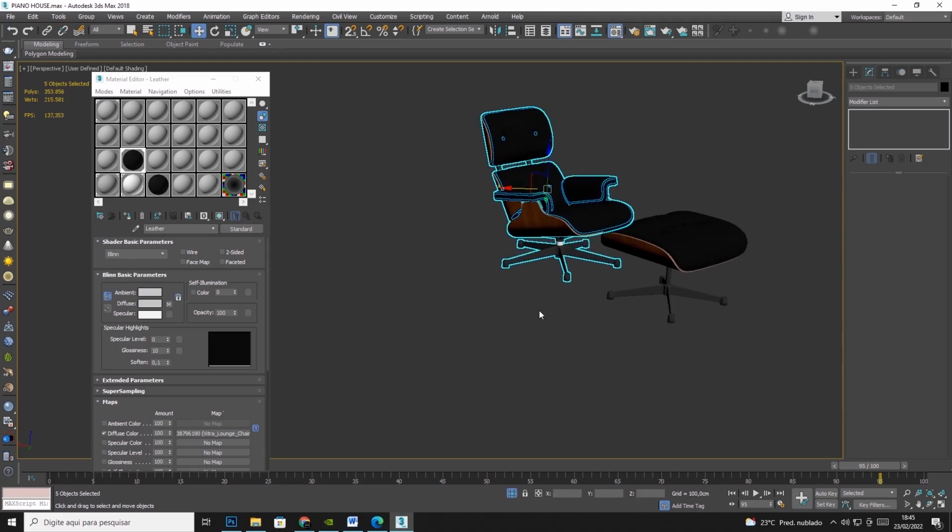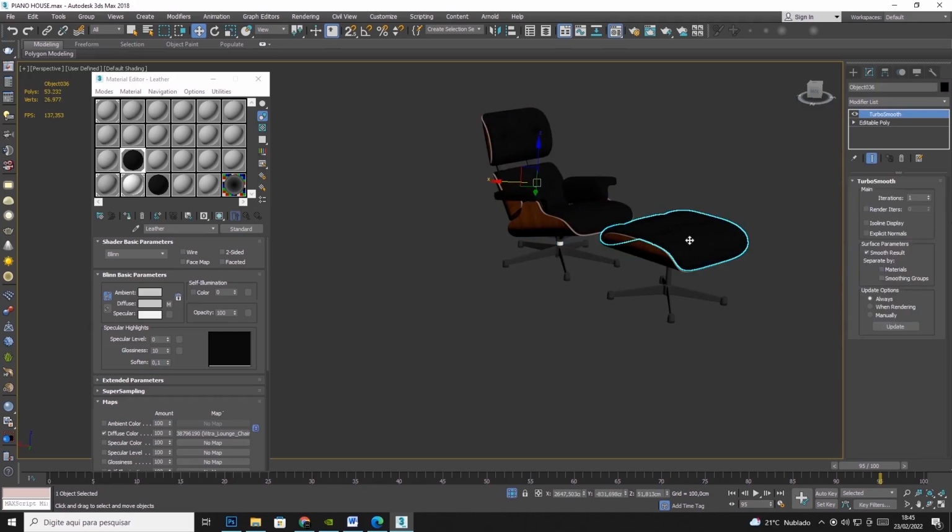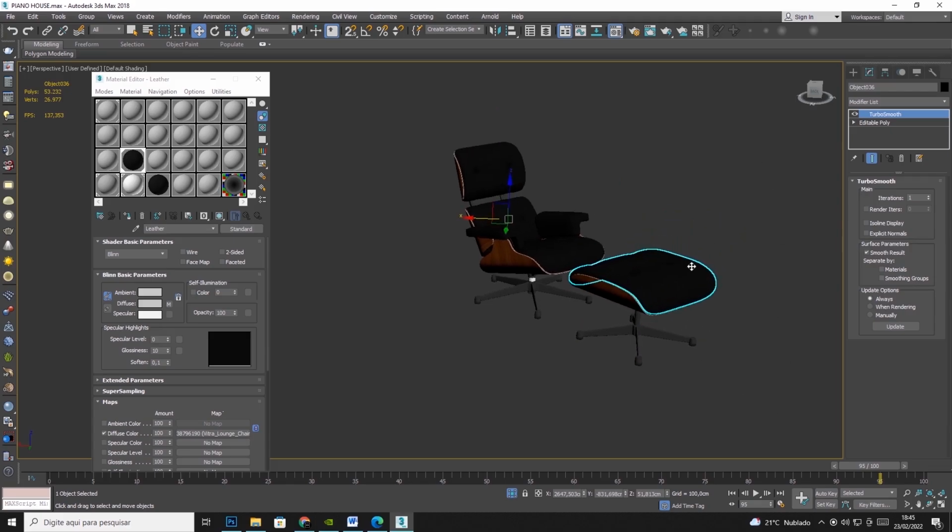On Unreal, we also have the option to ungroup the object, but in my point of view, to do that inside Unreal is not very efficient. So it's better if we attach the objects. This way we can transform all the objects in one. We will understand the reason of these things soon, okay? So let's ungroup this and group and attach the objects, okay?